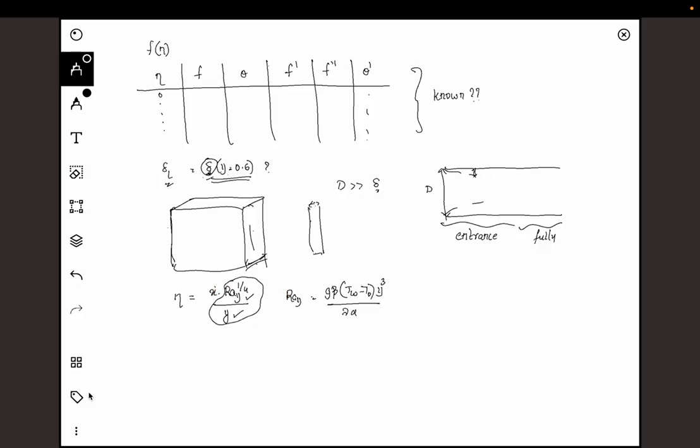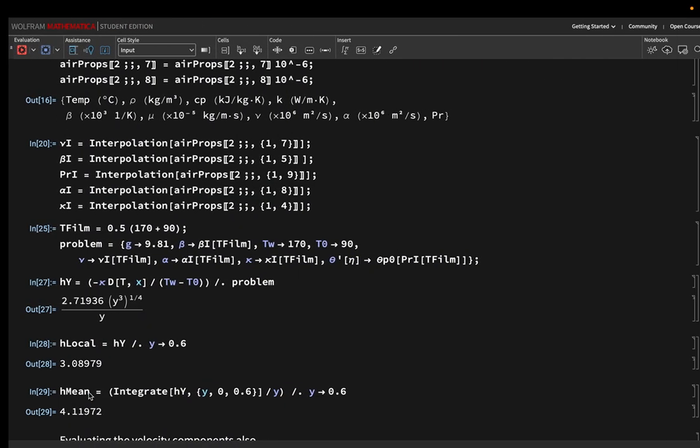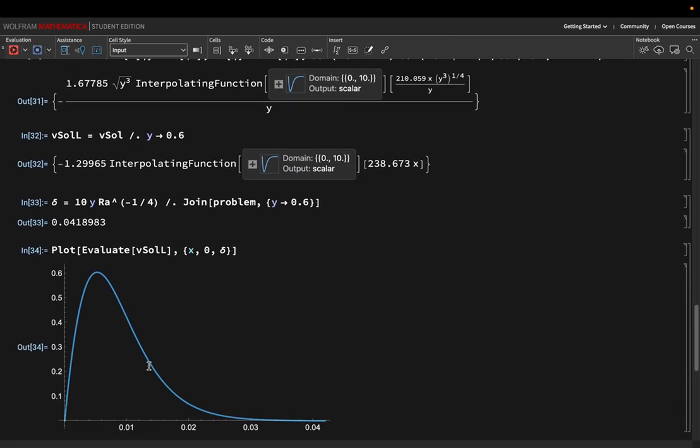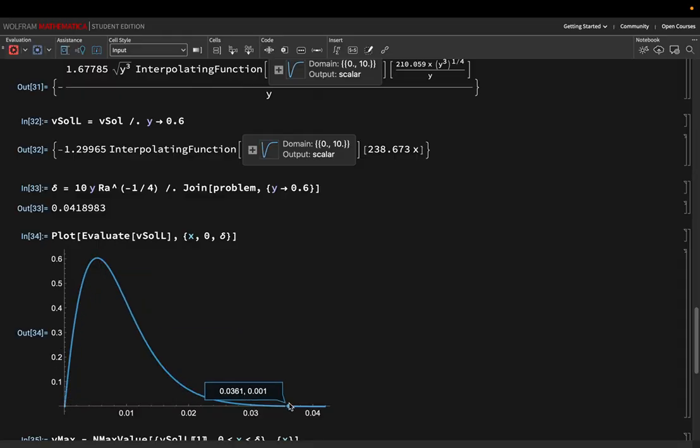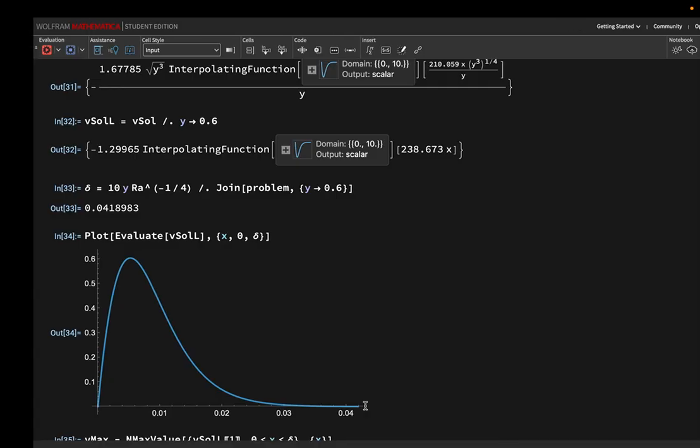The way we define delta is that beyond that particular delta, the velocity or the temperature becomes equal to 0. If it is delta T, it is the temperature; if it is velocity, it is the hydrodynamic boundary layer. That is how we have defined it. From the simulation, we found that the velocity profile I showed you just now is something of this sort. So beyond a particular point, the velocity will actually go to 0, and the corresponding eta value.